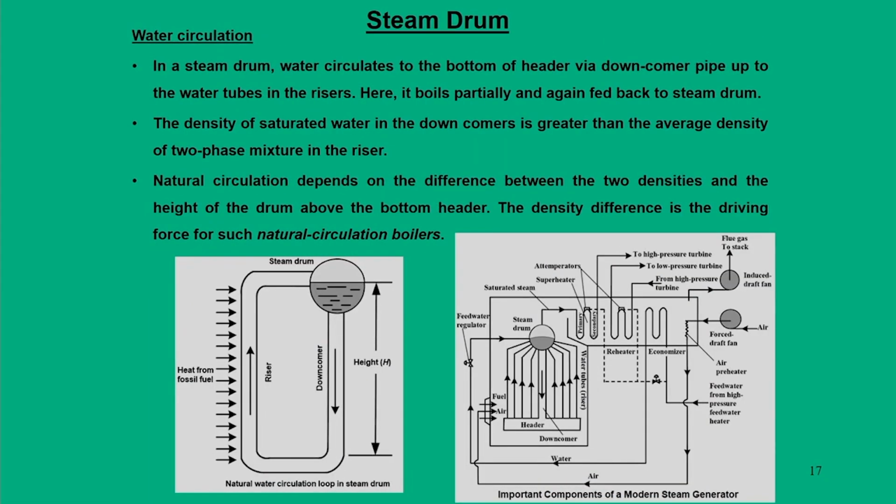So, this is all about how the steam drum operates, different mechanisms. Now, we will again talk about very specific components, like in the steam drum we have used the words riser and downcomer. Downcomer is for water to come out from the steam drum, riser is for steam that goes up into the steam drum. So, if you take one particular segment, it is represented in this figure.